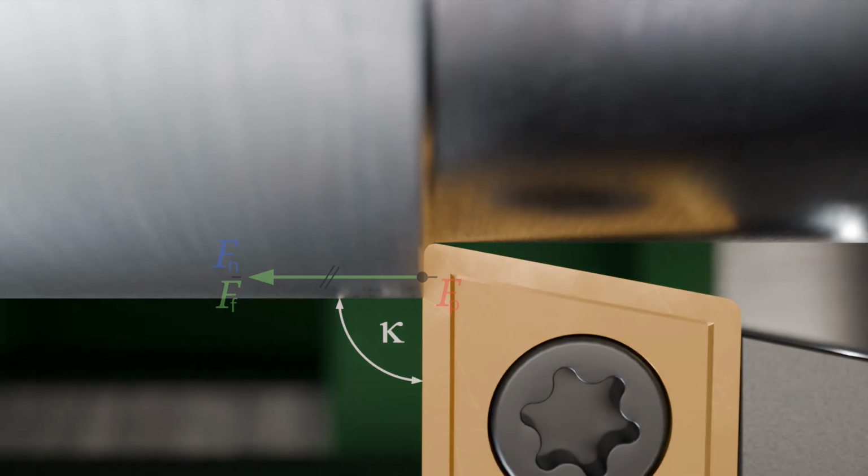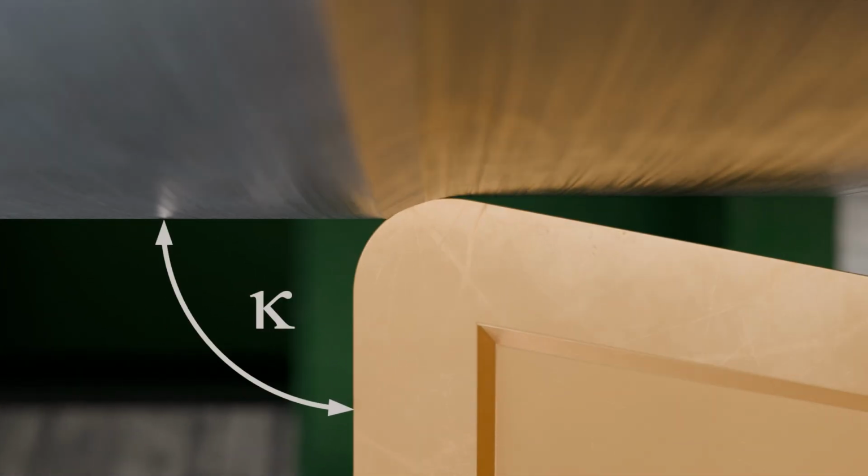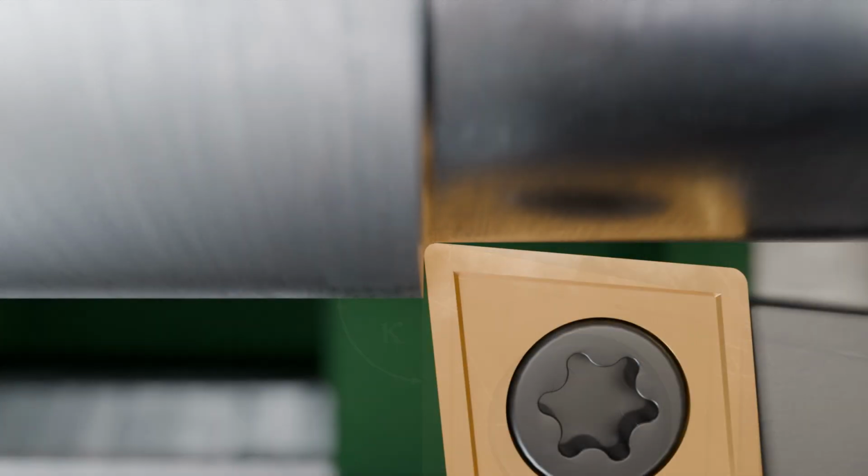This also clearly shows why the depth of cut should generally be larger than the corner radius. If the depth of cut is smaller than the corner radius, the cutting is no longer performed by the straight cutting edge but by the corner itself. The effective approach angle then decreases as the depth of cut decreases. This results in very large radial passive forces, which on one hand push the workpiece radially outward and on the other hand can lead to increased vibrations. Therefore, even during finishing, a minimum depth of cut must not be undercut, which should generally be larger than the corner radius. A few words about tool wear in longitudinal turning.